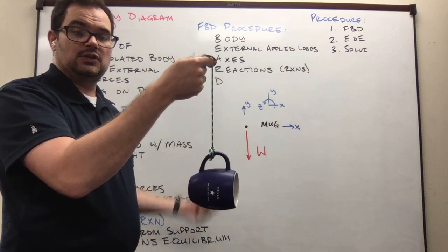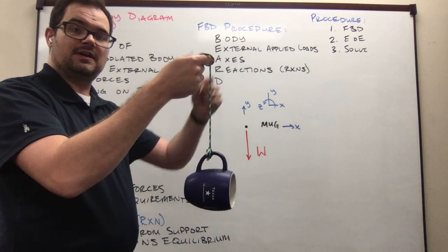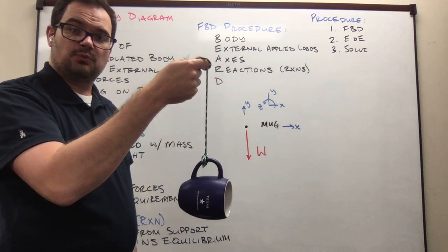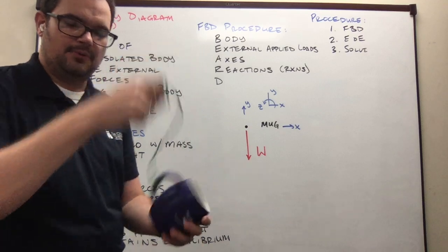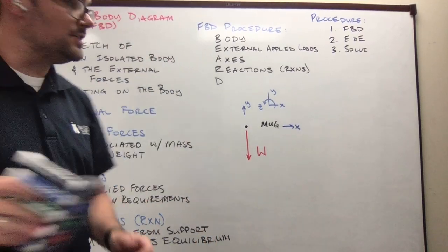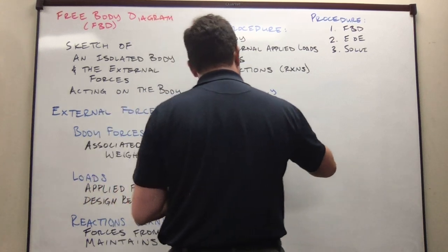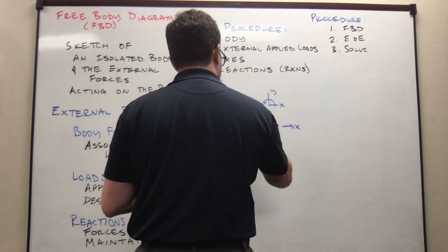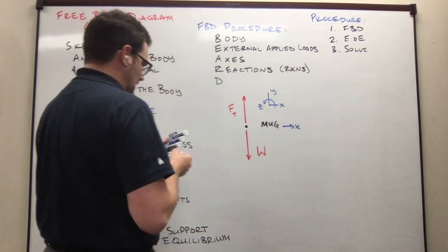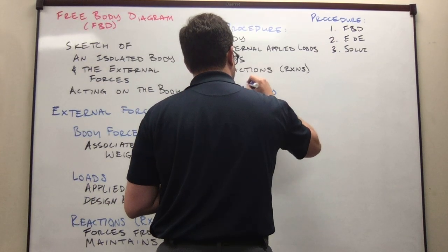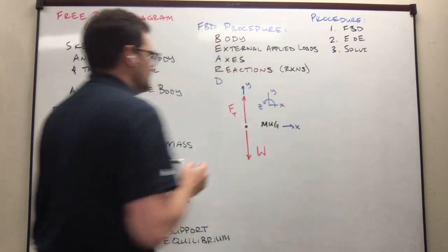We now know that we can use the position vector to find the unit vector to figure out the force along a line. In this case, it's pretty easy. The force just points up. So in this particular example, I can come over here and draw a tension force pointing straight up. Maybe I use a capital F to indicate force, and T is for tension.